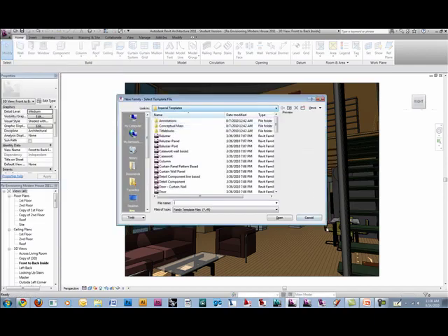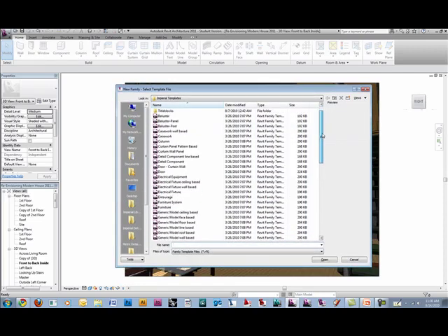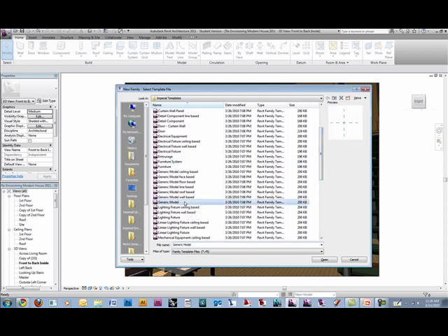When Family pops up, you have a bazillion things that it can be, anything from electrical components to columns, and it's what they say they are: site model, structural columns, whatever. Nine times out of 10, I would say generic model is the one you use. You can specify generic models to be ceiling based, like a light, or face based, which means it just has to find a face. The face doesn't have to be a wall or anything; it can just be a mass you created and you want to plop it on the side of it. Four, of course, line: you draw a line. Like I could make that stair a line-based family.